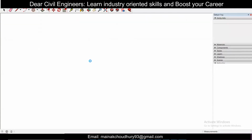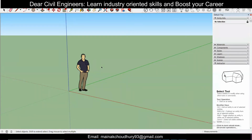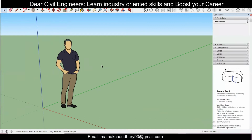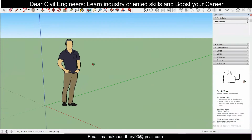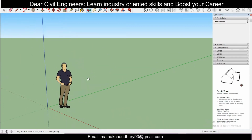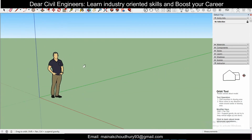A window like this opens here, and as you can see, there is a sample representation. Firstly, zoom in and zoom out are happening with your mouse scroll button. And if you just press the mouse scroll button and then move your mouse, it will rotate like this. So this is one basic thing. And if you want to pan, then just press shift plus your mouse scroll button. As you can see, this is the pan.